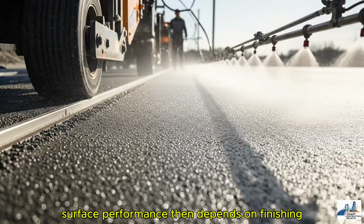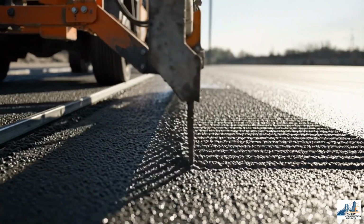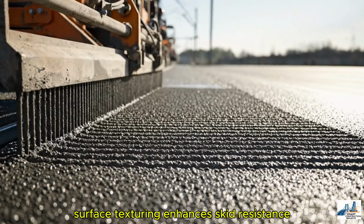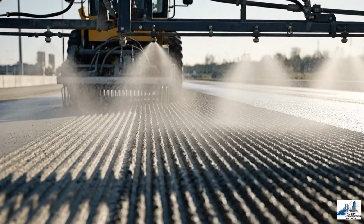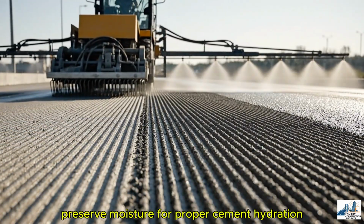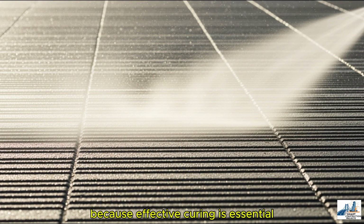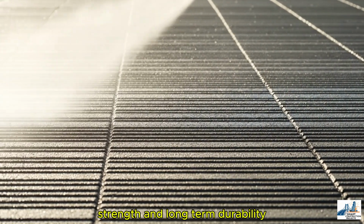Surface performance then depends on finishing and early age protection. Surface texturing enhances skid resistance, improving safety under wet conditions. Simultaneously, curing compounds preserve moisture for proper cement hydration, because effective curing is essential for achieving full design strength and long-term durability.